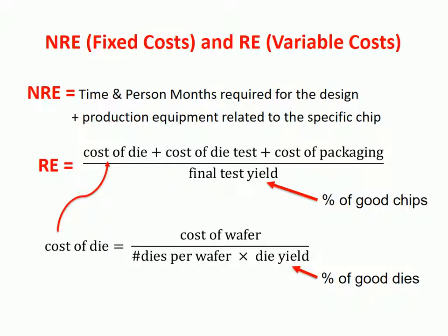Okay. The dies that are not good are those that, during the cutting, or because of some dust in the cleaning room, or because of some errors in the processes, have to be discarded. Okay, and just from a morphological inspection, they are seen to be not good. So there are two phases in which dies can be discarded. First, during fabrication, after just a morphological, physical inspection, and then after complete fabrication, after an electrical test, a functional test. Okay.